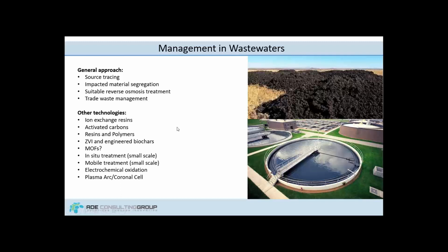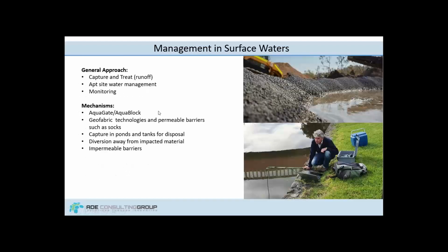These are methods that I haven't seen rolled out on a large scale. I've seen them in literature. So typically where we're aiming at the moment is pump and treat with activated carbons or resins or polymers. So these are the primary kind of methods we use to remove PFAS from water. Of course, this is not the source addressing way to approach things. This is a management process, managing the transport pathway.